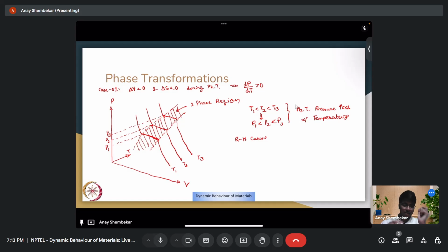As the pulse gets thinner and thinner, you can assume that whatever energy is being dissipated locally doesn't have anywhere to go within that short duration, which means for thinner and thinner shock pulses, it starts to closely resemble an adiabatic process. So no heat transfer involved. So the Rankine-Hugoniot curve can be approximated as an adiabatic curve.